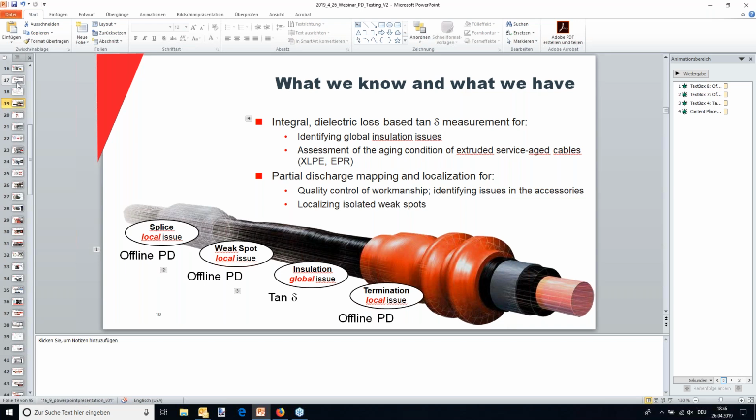Then the transformer creates a giant high capacitance cable because there's no way of isolating, so everything has to take the VLF voltage in those downtown network branches. But if you can isolate the cable specifically, also in URD and all of these applications, you should try to do that. And one more word on that, because Stephen said a practical question.